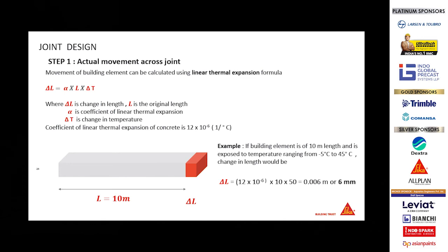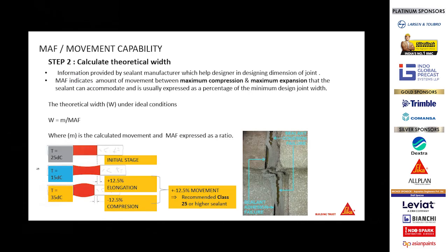But is it enough? For example, instead of 12, you have 13 mm. Is it possible to have a material which would compress to 1 mm and then expand to 12 mm or 13 mm? That material would be subjected to a stress of 1200%. Only a bubble gum kind of material could address that. But again, that would be only one time.